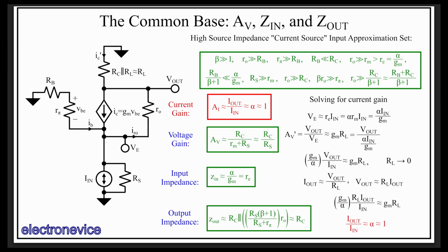For an ideal current source, the least stressful input to connect to it is a low impedance circuit, a short circuit. This causes the voltage to be zero and therefore dissipates the least amount of power, in contrast to an open circuit which would cause the current source to create an infinite voltage and thus dissipate infinite power. So looking back at our input impedance, we see it's little re, which is a pretty small resistance, good for an input to an ideal current source.